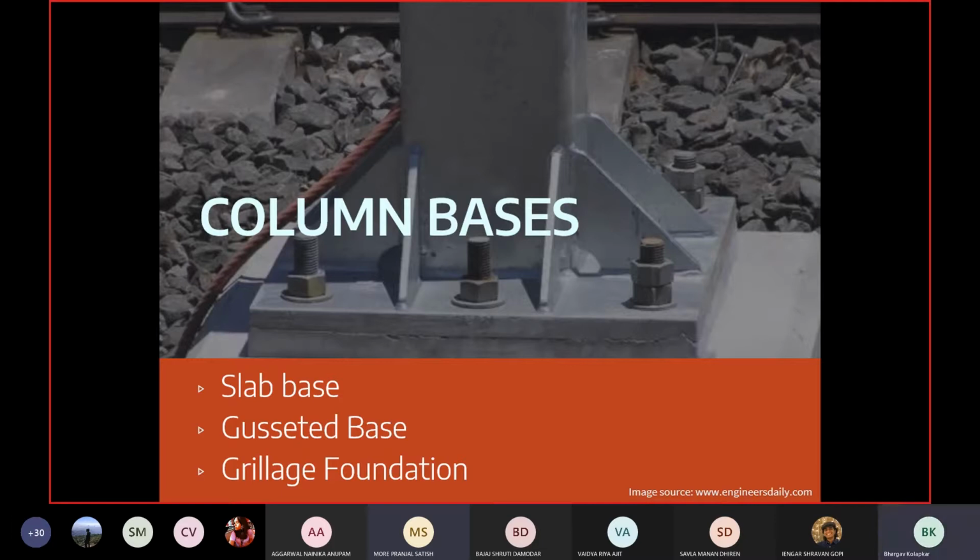Okay. So your answer is partially correct: yes, there has to be something to disperse that load, but the reasoning can be better. Irrespective of what material you use for columns, steel or concrete, it does not really matter. What matters is that you really disperse the load. A concrete column would carry more or less the same load, or slightly larger, for the same structure. But the question is not the load here.